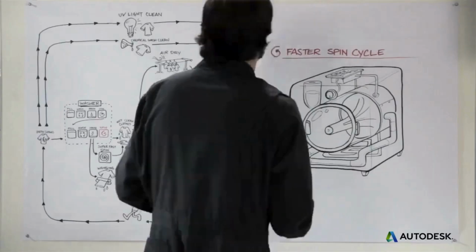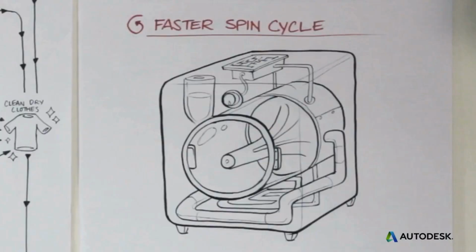Once you've chosen a solution to develop, you'll begin solving all kinds of technical engineering problems. For example, spinning the washer faster may require a different material or may create the need for vibration suppression, which brings up new costs and impacts. This time we focused on energy use because that was by far the biggest impact of the dryer. But you may want to repeat this again and focus on the next highest design priority, which in your case might be materials or durability.